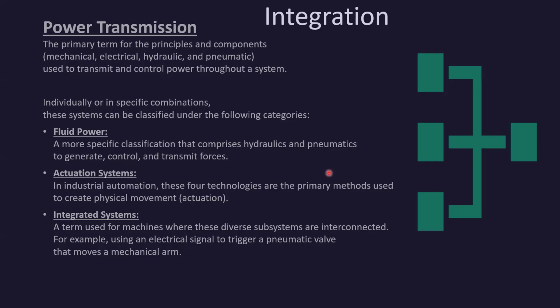So a pilot could be actually a trigger, or sometimes it is called an actuator. Right? So we are triggering or actuating, and in the conceptual diagrams, or the pneumatic diagrams, or the hydraulic diagrams, if somebody really wants to follow the rules and be really cute about that, those pilot lines would be drawn with dashed or dotted lines, usually dashed lines, to indicate that this is not the main power flow, it's actually a trigger or actuator.